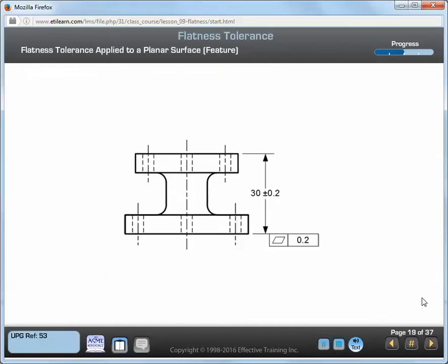In a flatness tolerance applied to a surface application, 3 requirements must be met. Size, rule number 1, flatness tolerance. The size dimension requires that the actual local sizes and the rule number 1 boundary be verified. The flatness tolerance requires that the flatness deviation on the bottom surface be verified. Let's take a more in-depth look at each of these requirements.